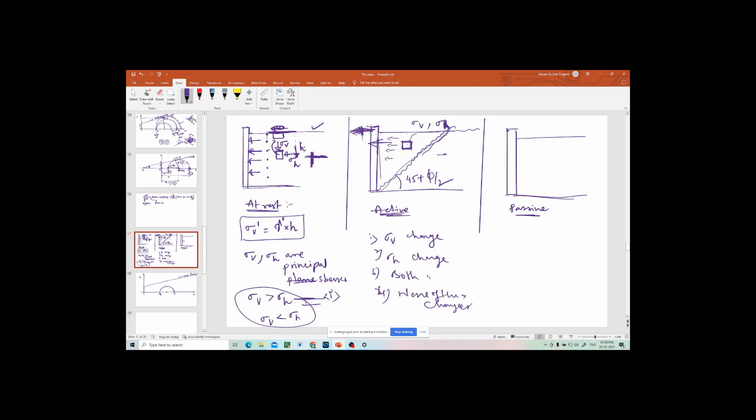element is subjected to some vertical stress and some horizontal stress. Now, if you see the top of the layer, the top of the earth, there is no shear stress here. There is no shear stress in this direction. And if you go below this element, normal stress is slowly increasing, from 0 to some value. How is it increasing? It is increasing in this manner, gamma into h. So normal stress is only there at any element, but there is no shear stress on the horizontal plane. So that plane is called a principal plane.